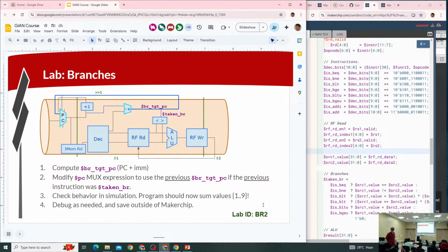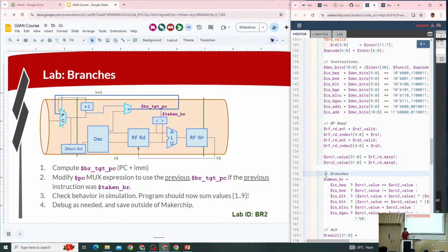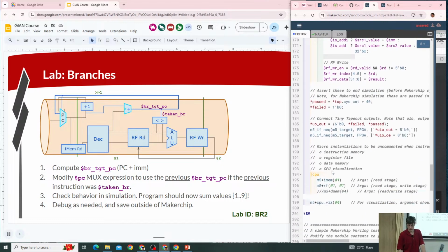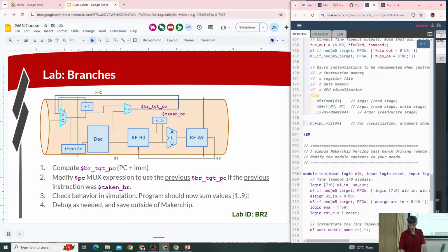I wanted to note, somebody was observing also that the visualization in the default template, I didn't realize this, is configured to visualize what's happening to the instruction that's in stage 4 of the pipeline. Let me see if that's the case here in my code. Yeah. So this viz macro is instantiated with a parameter at 4. That's causing the visualization to represent the instruction at stage 4. Right? So the visualization is actually causing this whole pipeline to extend out here, and it's representing that.